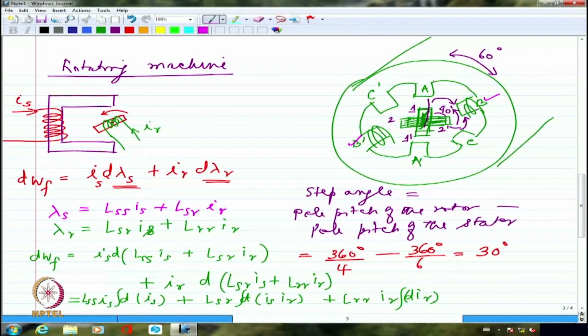The air gap path basically will not be followed as much as possible. If I try to look at the magnetic field lines under aligned condition, it is going to go like this. This is how the magnetic field lines will be. So please understand that the coil inductance depends upon how much is the air gap that is visualized for a magnetic circuit or magnetic field line. So the magnetic field line actually will pass through really minimum amount of air gap when the stator and rotor poles are aligned.